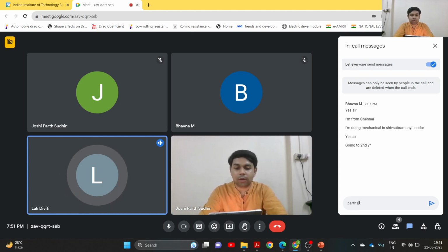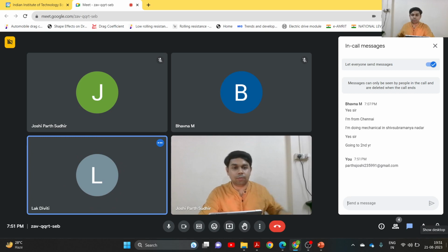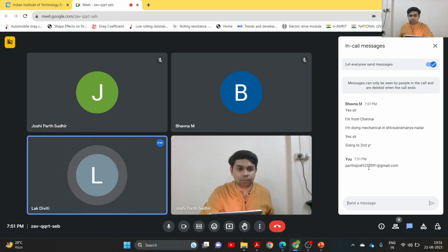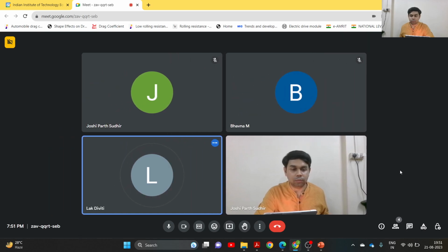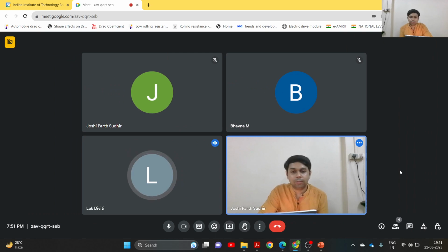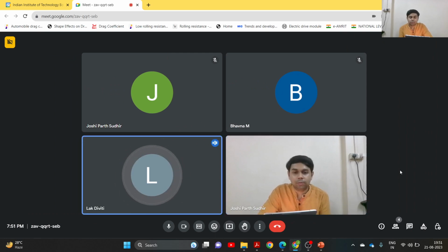We are using this transducer, sir. This piezoelectric transducer and accelerometer. We are measuring the casing vibrations on gearbox, steam turbine, generator, and we are also using velometers. Similarly, we are also using MPUs, magnetic pickup units, key phasers for speed reference, and LVDTs for vibration measurement.